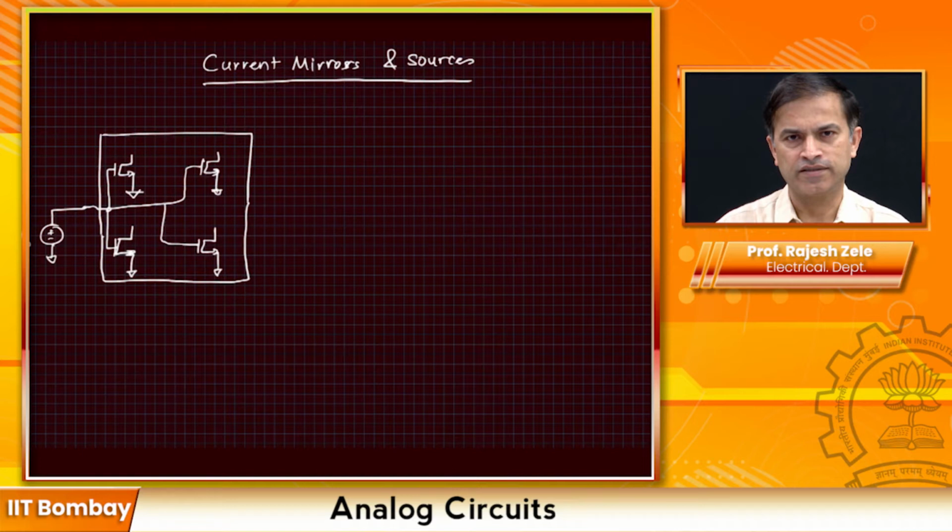It may go to different locations on the chip, with different resistance in that path. If there is any IR drop in that ground path, the amount of current will also change in each case. This is not a very desirable situation. So don't do this. This is not a good way to bias your transistors and create current sources.